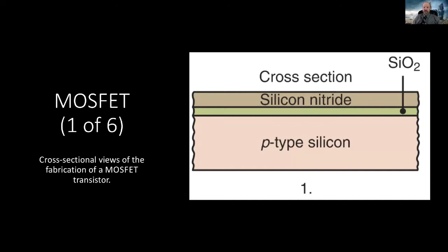So you basically put the pure silicon wafers in a furnace, and then you heat it up to 1100 degrees Celsius or so, and you cause the silicon to rust and put a little oxygen in there with it, okay? So you can rust the crystalline silicon. That's called oxidation. So you create SiO2, silicon dioxide, and you create a thin layer of oxide.